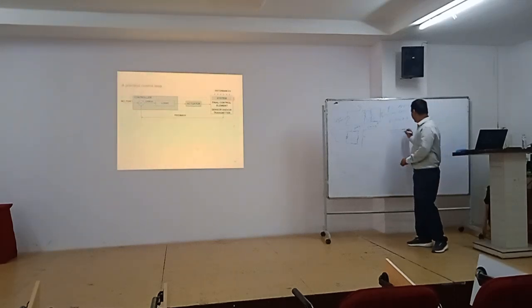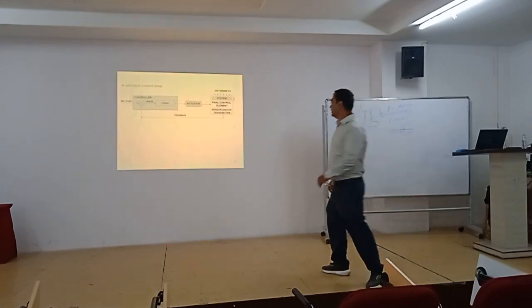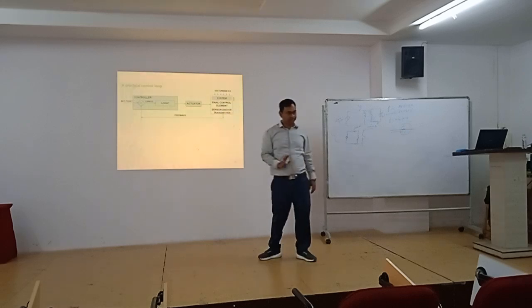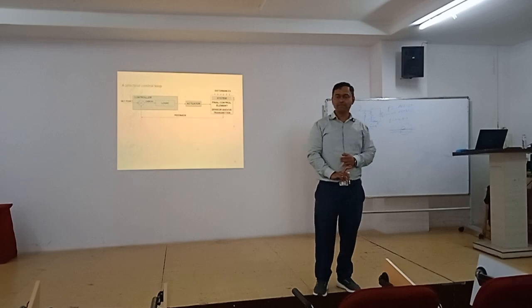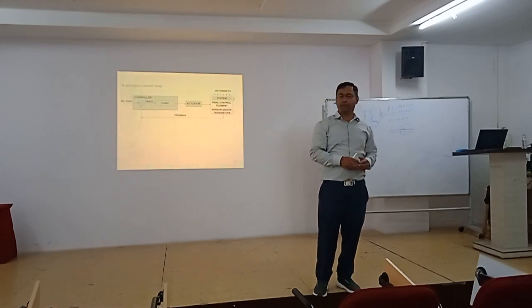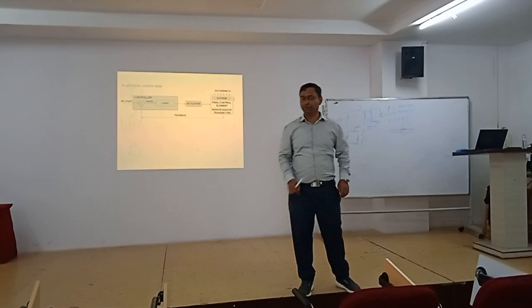So you will put one flow sensor to measure the flow. That flow sensor will give a signal to the controller. Then we will enter the set flow from SCADA. And how can you change the flow? How can you increase or decrease the flow?